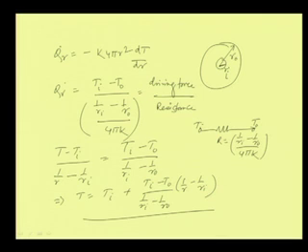Now, exactly the similar kind of temperature profile we can also find out, as I told you, by the general conduction equation. If we write the general conduction equation again, we know that grad square T plus Q dot gen by k is equal to (1 by alpha) del T by del t. You may just go through and find out the total equation, which we have discussed in the previous lectures.